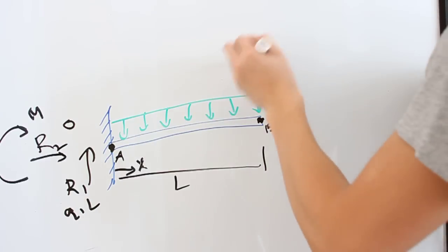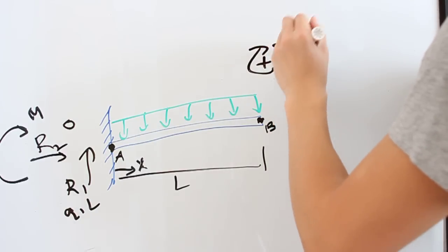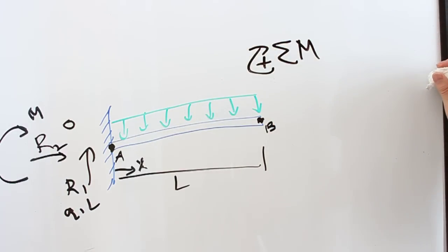Same kind of equation, given this direction positive, the net moment. For moments, when you do this equation you have to choose a point about which you do the moment. Usually you care about relevance, so if there's some point in this body which can possibly move, that might be a good place to check the moment, but you might also do it more strategically to try to get rid of extra forces you don't care about.